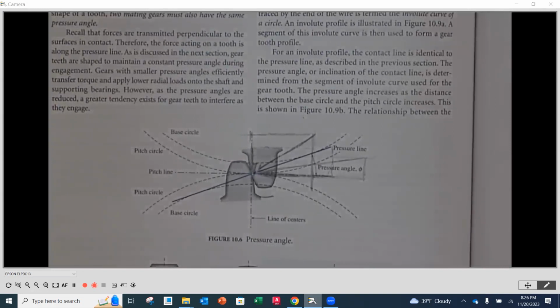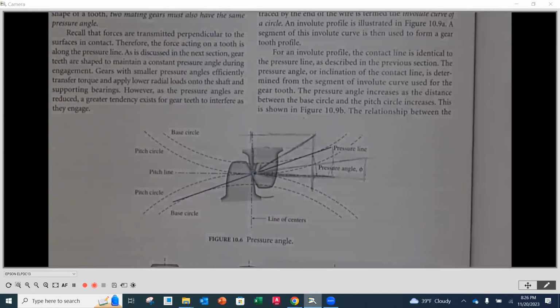Why wouldn't you just do everything? Sometimes like they're getting a lot of moves, high speed. That's exactly it. Yeah, thank you, Jesse. Yeah, so what you can have is they're going to be the bigger, chunkier teeth that are going to have the higher pressure angle. They're going to need more force to move them around. Yeah. And what? Like high torque. Exactly. Yeah. And so 20s are usually your first round that you're going to go with.